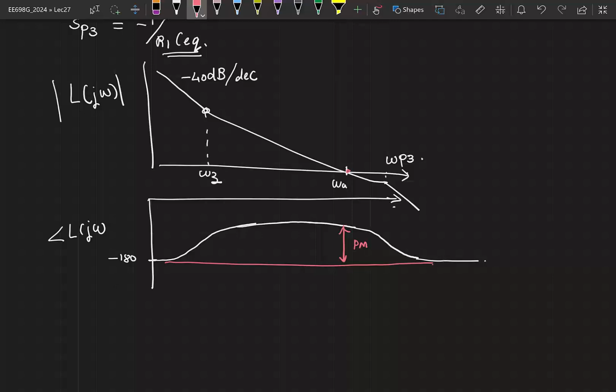Now I have one last question on this. Let's say there is a phase margin constraint given to you and it turns out that you can meet the phase margin constraint whether you put your omega u somewhere here, or somewhere here, or the third option, in this region. I'm giving you 3 options. If you had a choice, how would you design? Where would you put your omega u in this curve? By adjusting the gain, you will be able to shift the position of this curve and get an omega u. If you had a choice, where would you put your omega u?